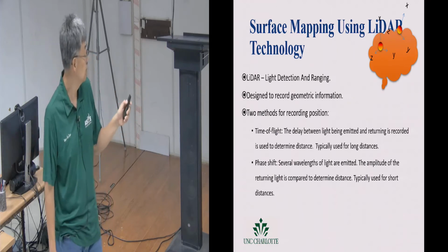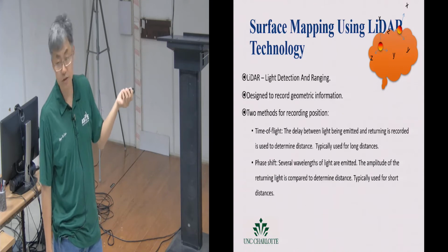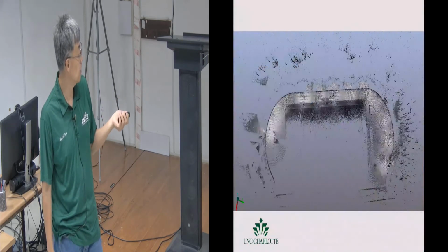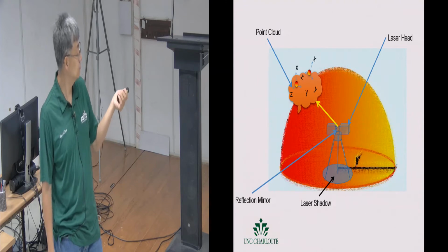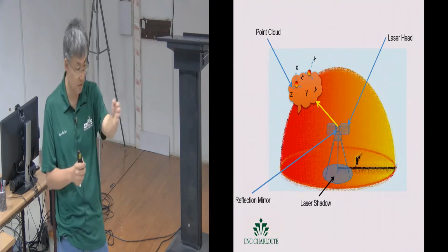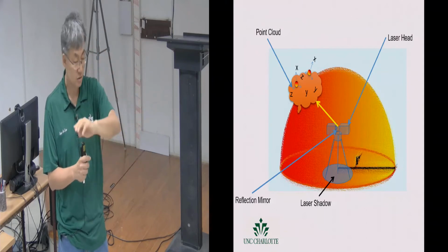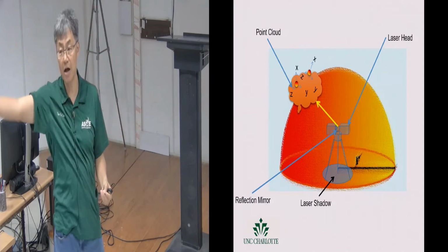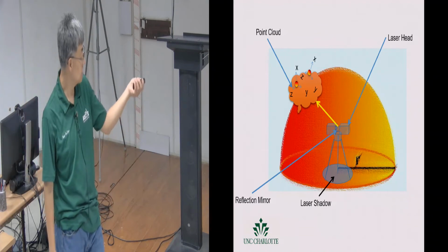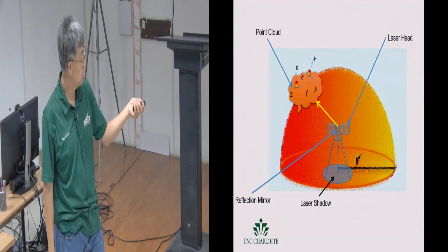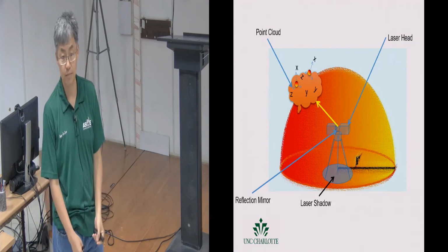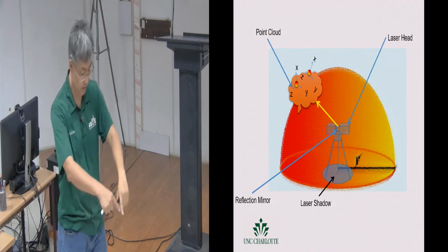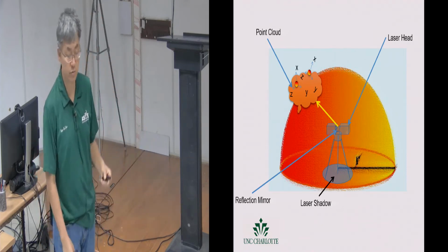Now I'm going to show again the LiDAR technology, but from a little bit different perspective. These are most of the things that Navneet discussed yesterday. Okay, oh, go too fast. The LiDAR system: yesterday he showed an animation where the laser scans this way and this way. The effect is that you actually create a half hemisphere. The ground, of course, you also scan, but what you will not be able to see is right underneath the laser. Depending on the height of your laser, you are actually creating a circle on the ground.